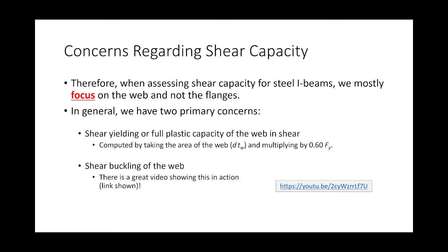It's the same reason why in concrete design, let me pause that. It's the same reason in concrete design, if you did the same thing, you would find a crack going this way, the other way. The reason is concrete is a material that is very weak in tension, but strong in compression. So instead of failing this way, it fails this way. It opens that way, so you get a crack under tension. That's why inside concrete beams, you put stirrups to withstand the resulting shear.